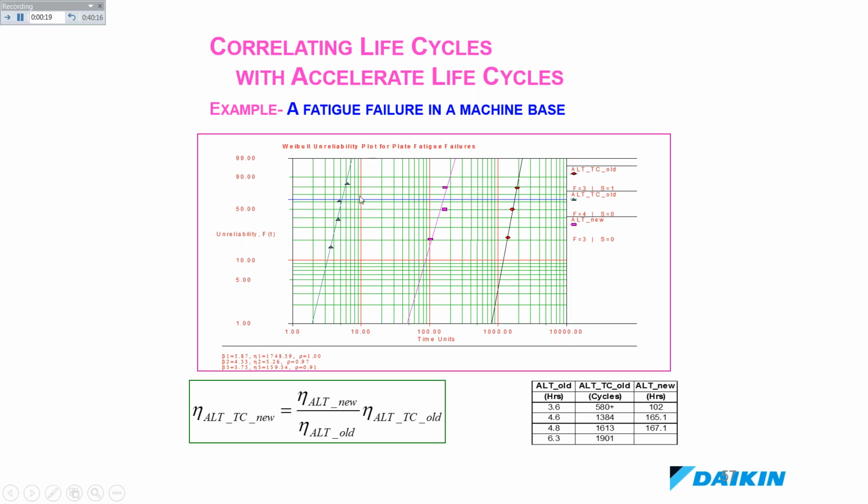And we improved our product until we passed this, because we knew we transferred our real life reliability into number of revolutions, the washing cycles to revolutions. And then we launched this product because we passed our reliability target in terms of the number of revolutions in the fixture, which is actually passing our washing cycle target.